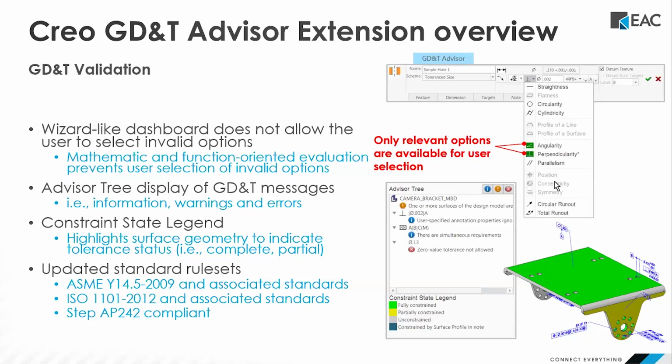So if I pick on a surface and say, okay, maybe this is your first GD&T, so it's a flatness, and I'll highlight it here in green. These are your choices that most logically will apply to the geometry that you selected. It actually looks at the geometry and the GD&Ts you made previously and also works off of those, saying this is most likely the most advisable GD&T to place in there. So it's giving you throughout the experience the correct things to do, and it leads you down the path. You don't have to be an expert, and that's really the whole idea.